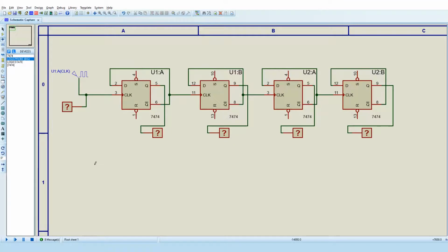So now I'm clicking on junction mode just to make some wires for outputs A, B, C, D and not A, not B, not C, not D, just so we can tap off from them with our logic gates. So it's kind of like having a bus for all of the Q and not Q outputs. Remember, the not Q outputs are the complement of the Q outputs, so they serve as our not A, not B, not C and not D variables from flip-flops 1 to 4 respectively.